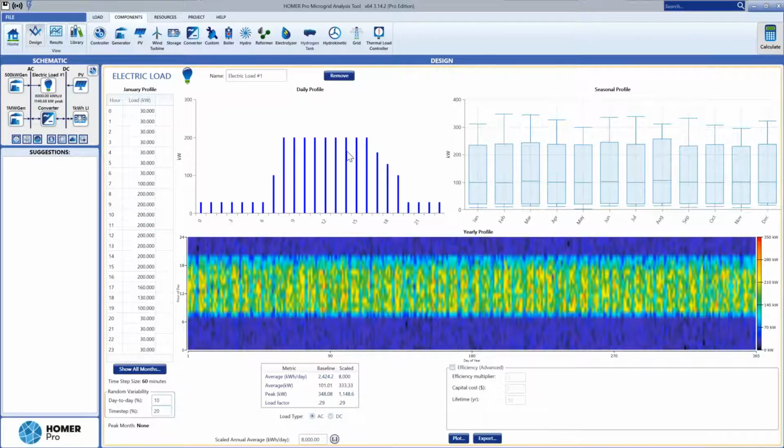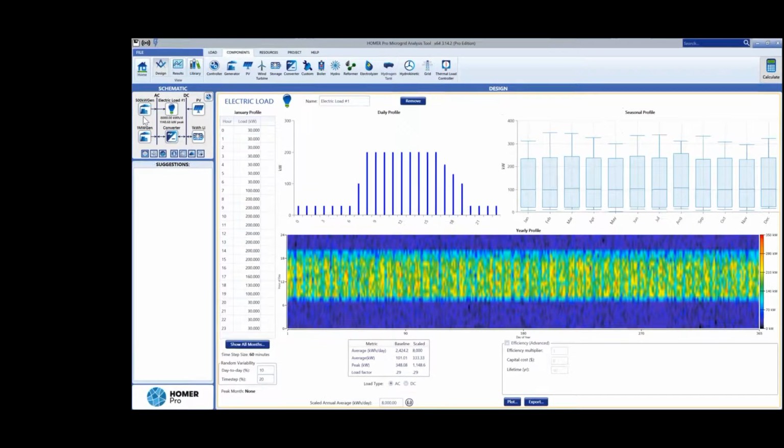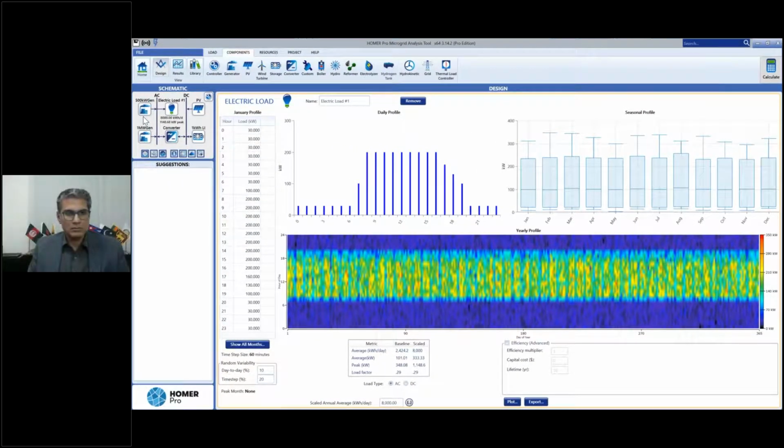So I just set up a little model here. I used a commercial load. I put in PV and battery, and I have 2 generators. And we recommend this if you're with 2 generators. It might not be essential if you wanted to model a system with 4 or 5 or 10 generators. It will run much faster if you use this generator order dispatch.